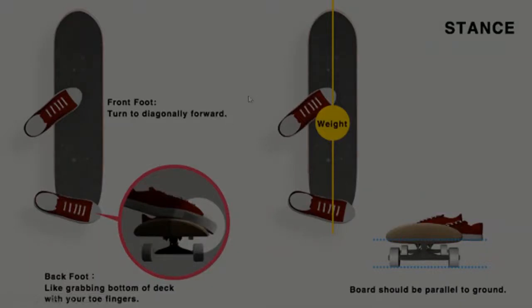So for our weight distribution of the person, after doing some research and reading, we find that the best stance that a skater has is when they have about 60 to 75% of their weight on their front foot. So this allows for them to have their center of gravity closer to the center of the skateboard and allowing them to control it. So when we do our calculations later, we're actually going to put 60% of the person's weight in front and 40% in the back.